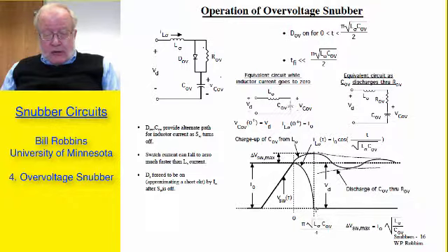The current is now 0 through the inductor, and from here on the current will stay 0. After this time, which is assumed to be much longer than the current fall time, we then have the equivalent circuit shown to the right, which is a series RLC circuit, and so it's a damped sinusoidal response.